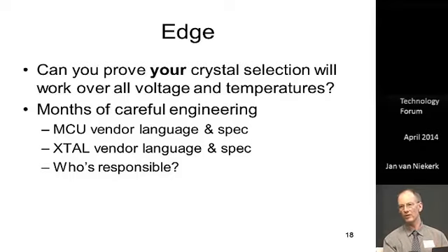And in fact, if you want to be 100% safe, buy a crystal oscillator. It's well worth that extra 10 or 20 cents, because the guy who sells you a crystal oscillator has to warranty that that thing always works. So then it's not your worry. But anyway, I know for a cost thing, we like to put the crystal on, but don't just slap a crystal on that board. It's a trap.